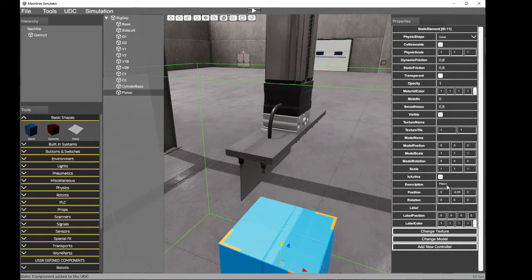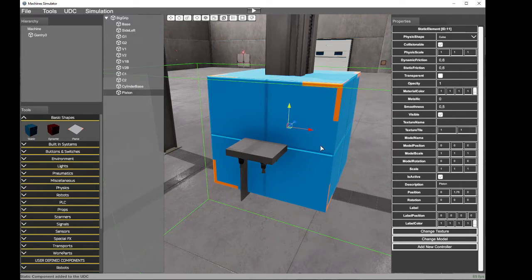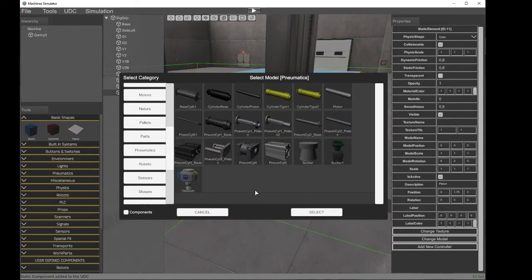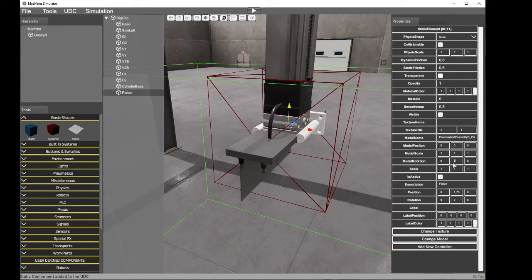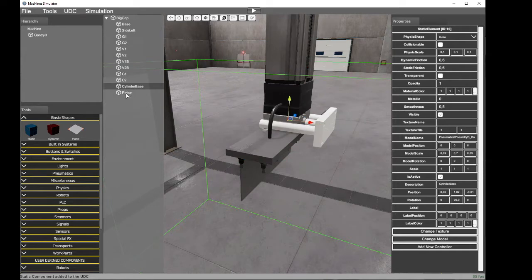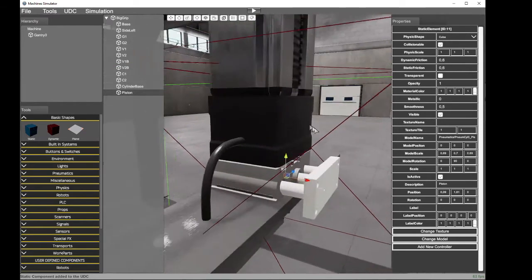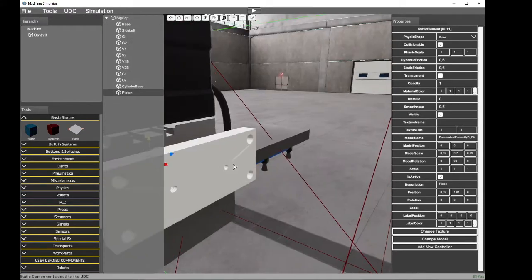Let's call it piston, and let's locate it in this position. Let's assign a model. This is the piston associated to the base. Let's change the rotation to 90 degrees and adjust the scale to be similar to the base of the cylinder. Zero point 0.69, 0.7, and length 0.6. Okay, let's adjust a little bit to be inside,